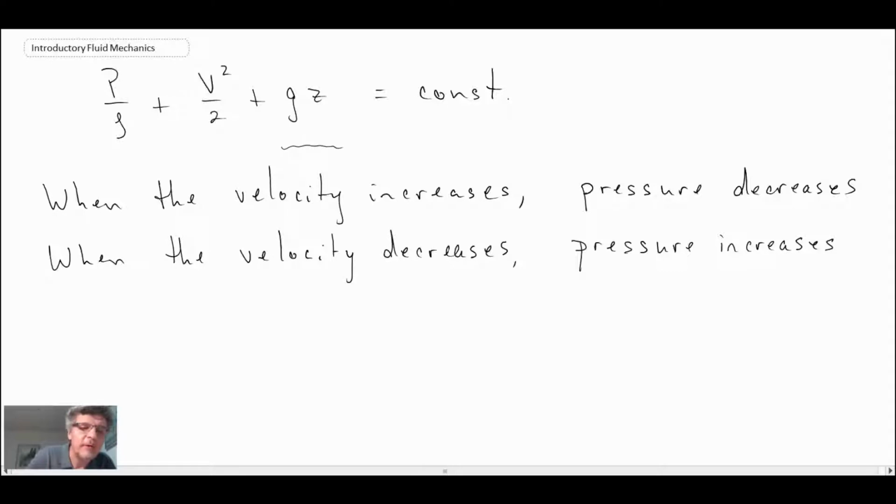So what we see with Bernoulli's equation is that when the velocity increases, so let's say the velocity was to go up, and let's assume that the potential change term wasn't really changing that much, because we're dealing with not a very dense fluid, what we can see is that if the velocity goes up, the pressure is going to go down. And that's a very important component or interpretation of Bernoulli's and application of it.